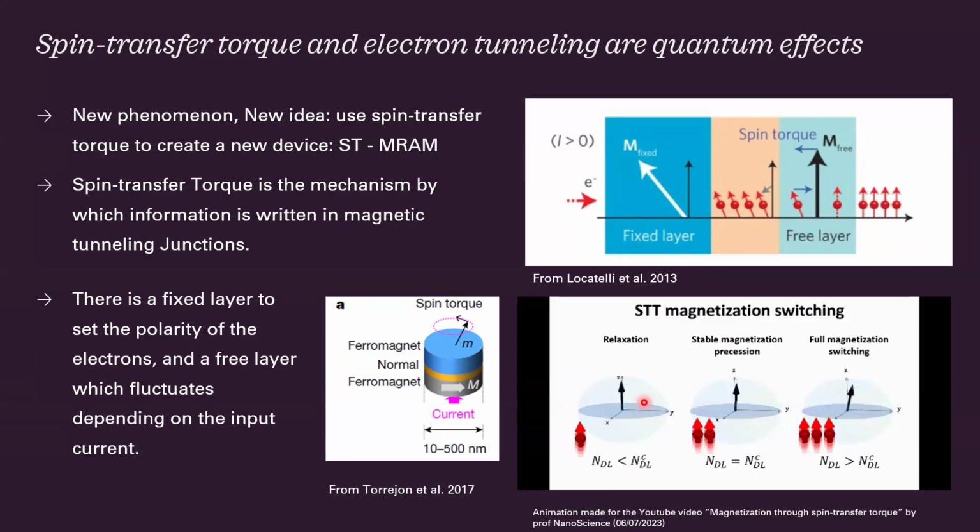And here we can see that if the torque is too small, the free layer magnetic moment is going to decay to its original state. But if it becomes large and actually reaches a threshold, it switches around and induces this radical change event. And this figure here just shows how we would expect the nano oscillator, like the spin transfer torque oscillator, to work, to look like.